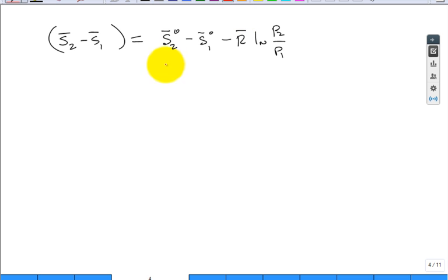Where do we get these? From the same table where we got the H bars. Yeah, it's the same gas table. Hey, I don't understand what this naught is. Let's just throw it out. It's meaningless. S with a naught or without a naught, it doesn't matter. Just like S with a bar, without a bar, it doesn't matter. No. It means something. It means low pressure. And so the pressure effects are incorporated in this term on the change in the entropy. All right? Okay.